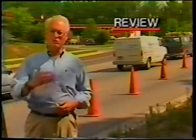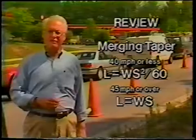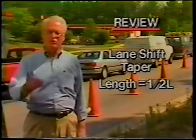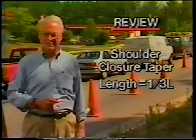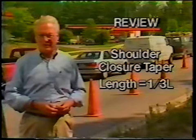Let's briefly review tapers and taper lengths. Where traffic on a multi-lane highway must merge, the required length is a function of the speed limit and the lane width. If traffic on a multi-lane road is to be shifted to a different lane, the taper is 1/2 the length of the merging taper length. When working on an improved shoulder, the required taper length is 1/3 of the merging taper length.